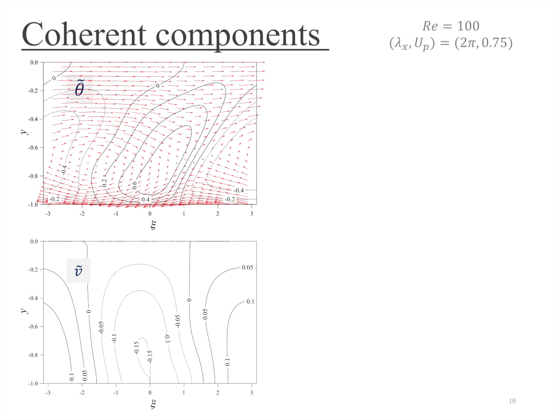Secondly, the wall movement at the speed of minus U_p drags the theta tilde contours in the upstream direction due to the viscous effect. And finally, the convection outside the near wall region transports the temperature fluctuation theta tilde in the downstream direction. As you can see, the upstream fluid motion close to the wall and the downstream fluid motion away from the wall result in circulation rolls, as can be seen from here.